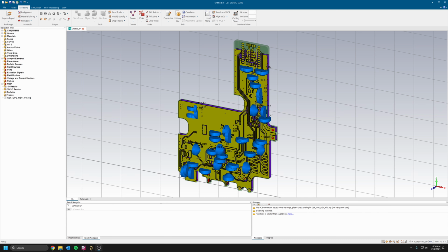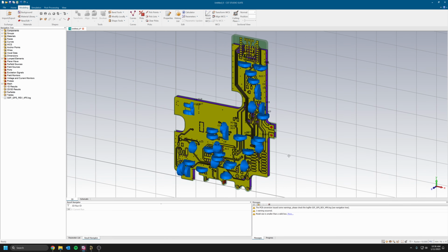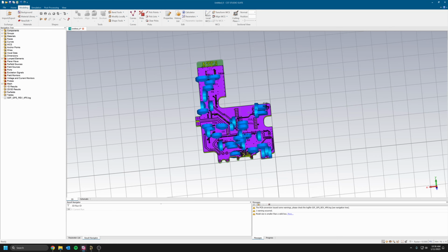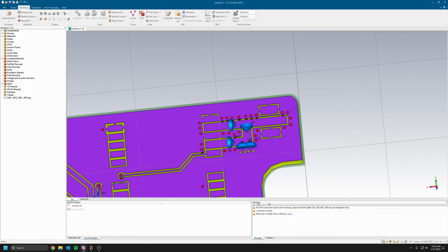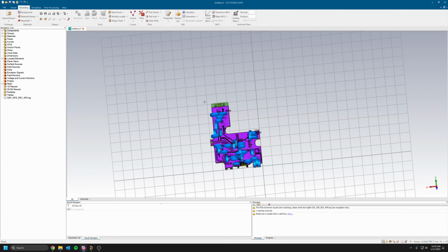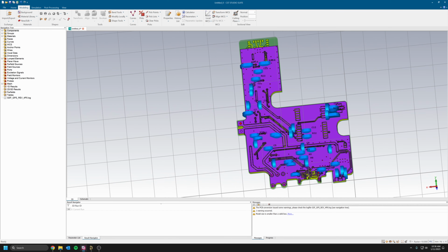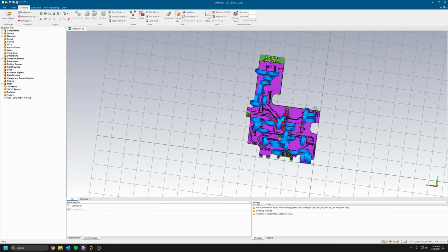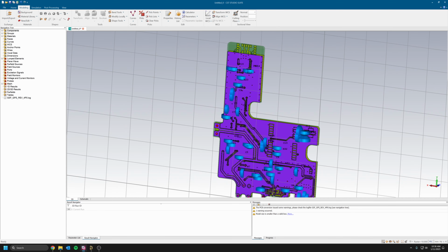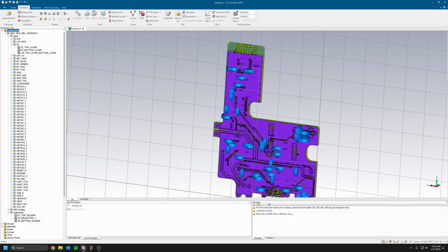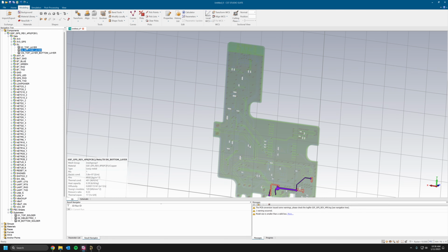Alright, so the first thing, like I said, we want to remove most of the circuit board that is not of interest. The part that is of interest is located here. So we want to simulate this part, and we probably want to cut most of the PCB here. Let me show you how we're going to do it. First, one thing we can notice is that every trace that is imported into CST is created as a different net. So we have all these different nets here that are independent.